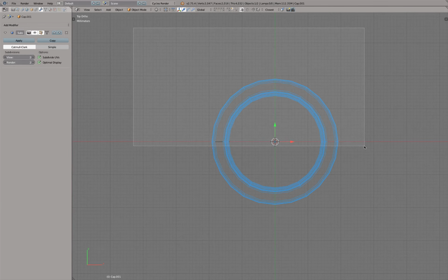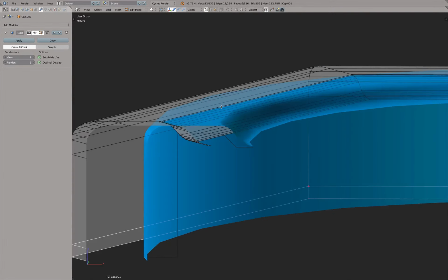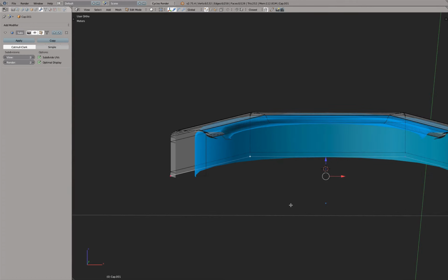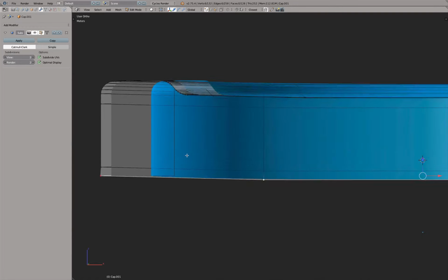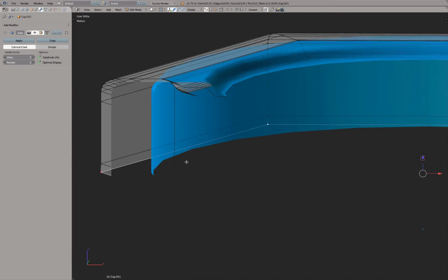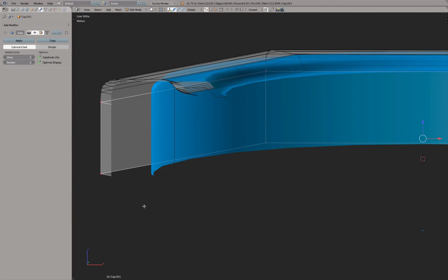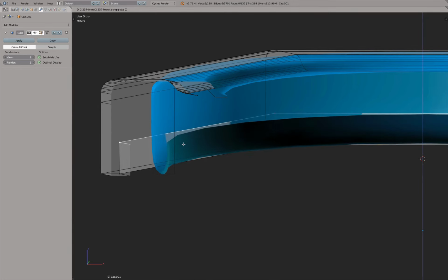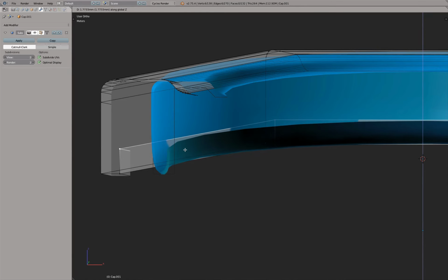And I'm going to make a cut section view this way, because when I now select a complete loop, even the stuff that is selected, you do not see, is then also going to be selected. And now I have the ability, for example, to do things like this, remove it, we don't need it. U, then E for extrude, press S for scale, and we scale this one in. And then E for extrude, and then G and Z, just Z actually. When you extrude, you're in grab mode, so press Z to go up.